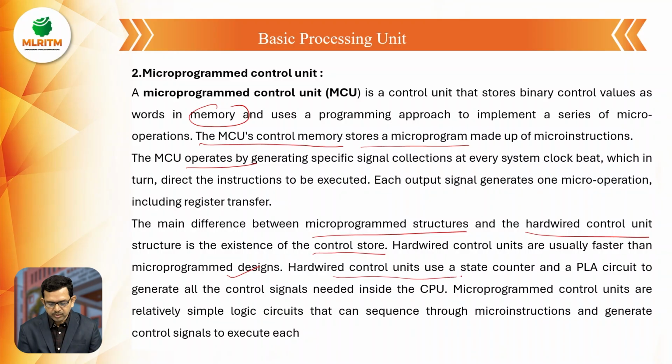Hardware control units use state counters and PLA circuits. They use mainly state counters and PLA circuits to generate all the control signals needed inside the CPU. So for whatever instructions are to be handled by the CPU, these two, the state counter and the PLA circuit, play a very critical role in executing them in hardware.